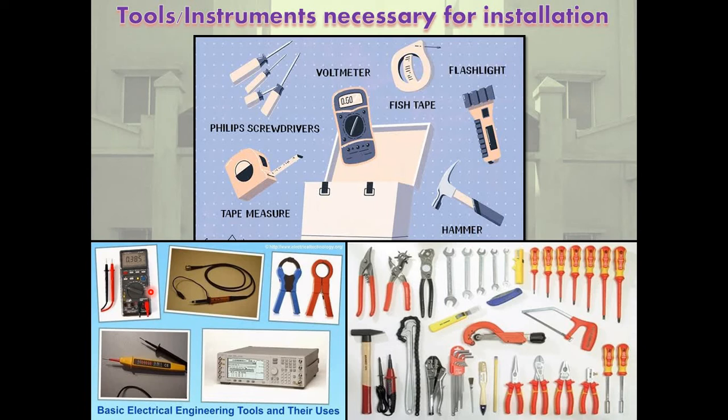Follow visual and written instructions on the panel. Equipment has signs and labels on them alerting employees to hazards. Be cautious while testing and replacing the components in the panel. All levels of voltage should be considered equally dangerous. Even the voltage level which cannot produce electric shock should not be ignored. We should check and confirm that the circuit is dead before touching it for repairing, maintenance, or any other work.